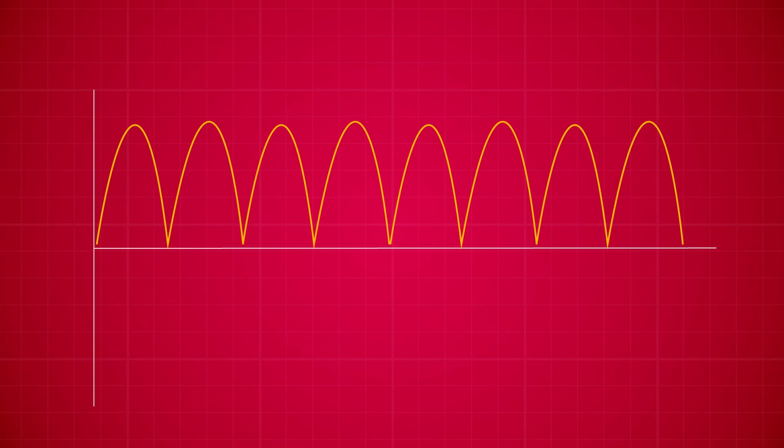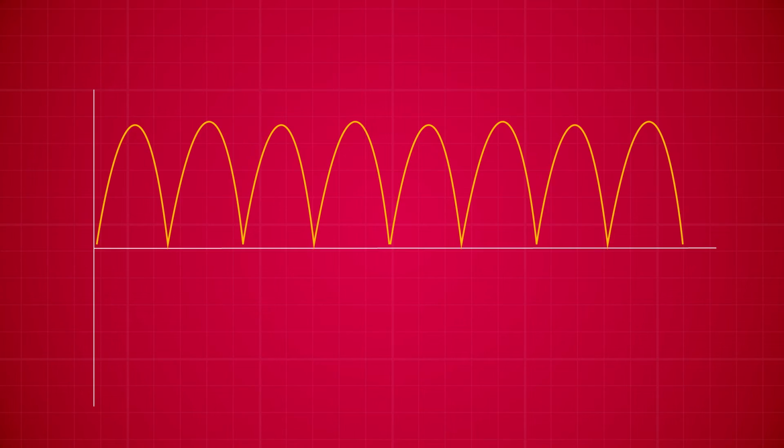The waveform will now look something like this, which can loosely be interpreted as the absolute value of the input sine wave. Because we use a center tap transformer, the output waveform has an amplitude half the input signal. Since the rectifier produces an output during both cycles of the input signal, it has twice as many positive cycles. As a result, the average value of our output waveform will be equal to the average value of our AC signal. Although the signal has now been rectified, we still have a change in voltage at the load, even though we want a straight DC voltage.